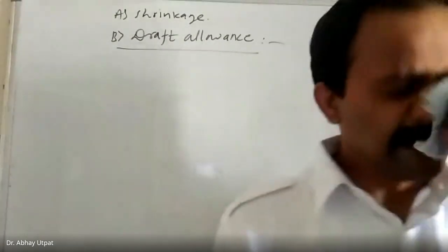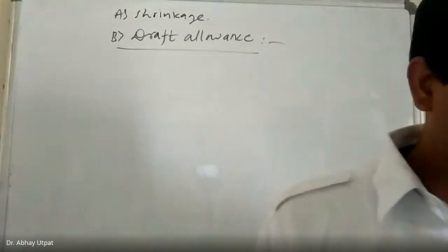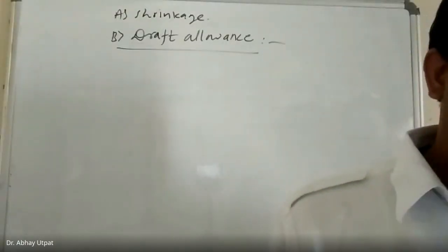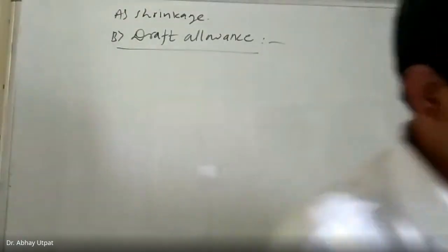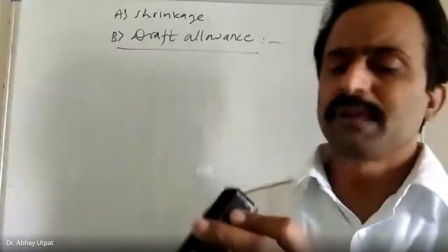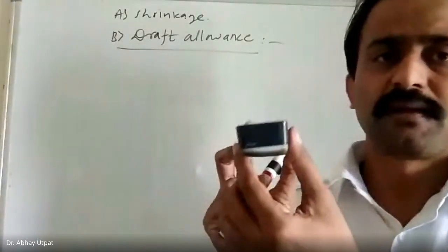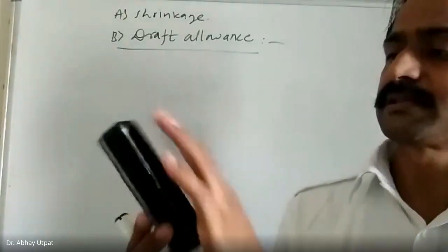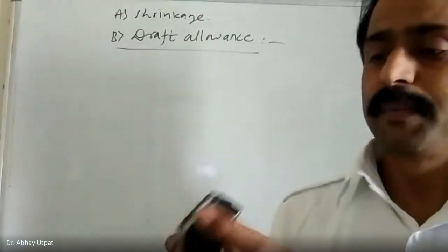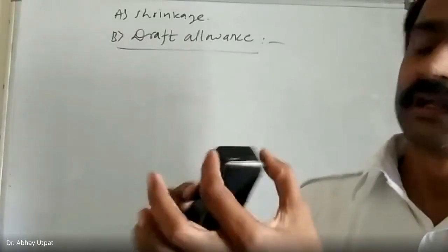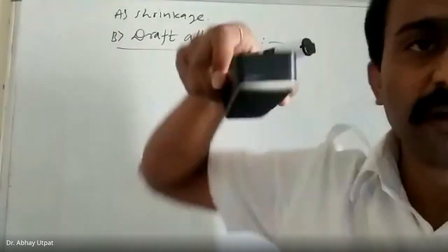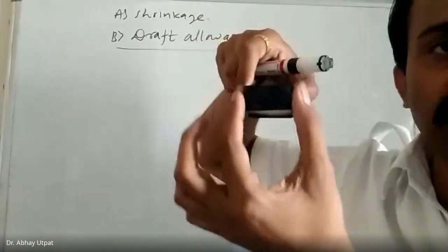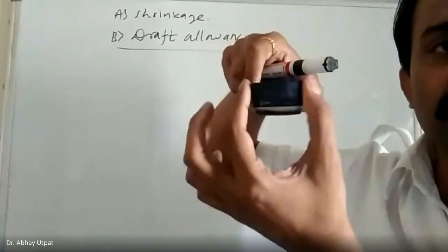Means which is your withdrawn direction. So your part, when you are putting in the part, even you see this duster, if you see this from outside, you may feel that yes, it is rectangle, but if you see it carefully, little draft is provided here. So your shape is not exactly rectangle, little taper is provided here.